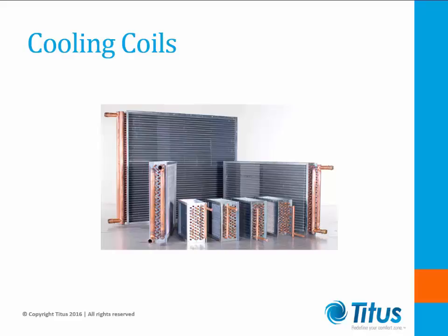One is moisture carryover. Above 500 feet per minute, condensate from the coil fins and tubes can be carried into the airstream over the drain pan. A good design starting point is 450 feet per minute. At this point, the unit can be turned up an additional 10% without running into carryover concerns. Additionally, velocity across the coil equates to the pressure drop. Lower velocity helps to minimize the unit pressure drop and thus motor horsepower requirements.